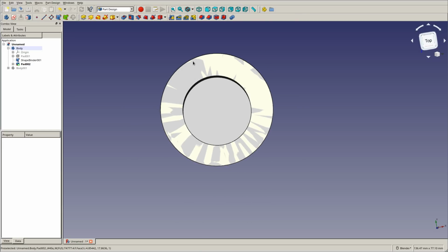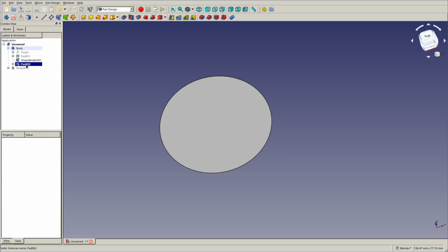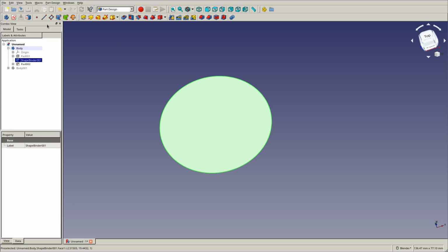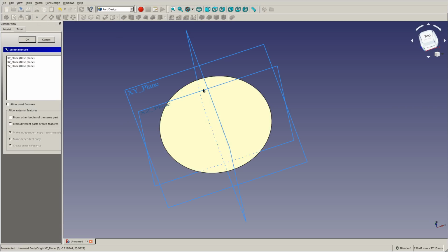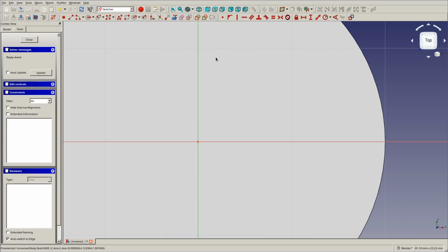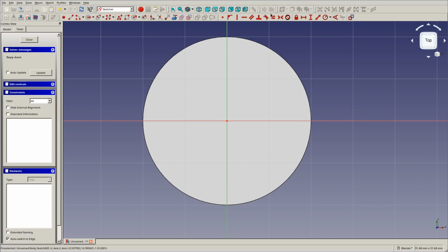And now we just need to do the blades. So again, I'm gonna need to map a sketch on this face, the torus-shaped face. But because I'm only gonna touch the edge, I can reuse again the old shapebinder. That's not gonna matter. Oh, I messed it up, so I click on the face first, then new sketch. So the blade looks like... actually, I just want to reuse the circle there, so...